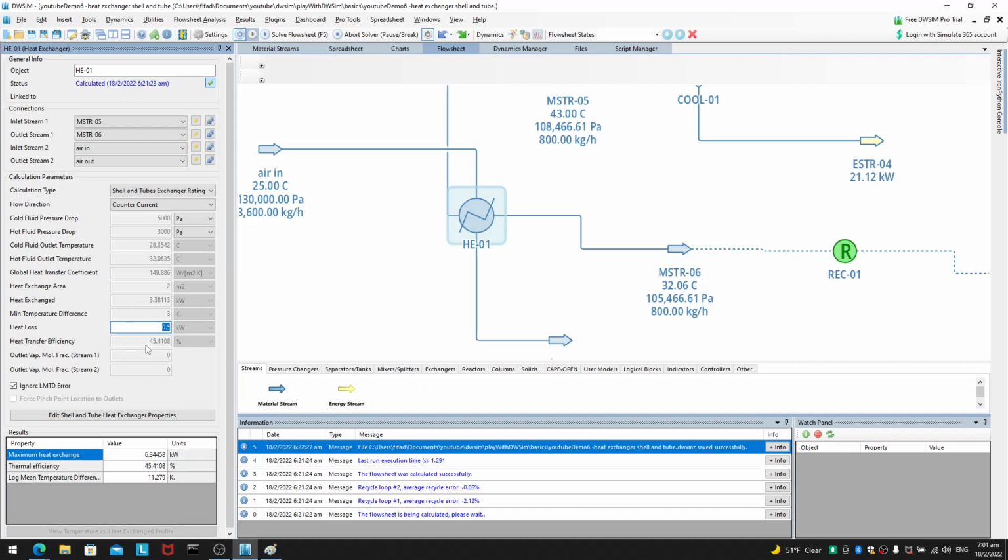because depending on your average temperatures of the stream and everything, your heat loss rate will again differ, right? Your heat loss rate will differ based on the surface temperature of the shell and tube heat exchanger, how good your insulation is, blah blah blah. Right? So of course you want to minimize this as much as possible. Okay? So this will play a role.